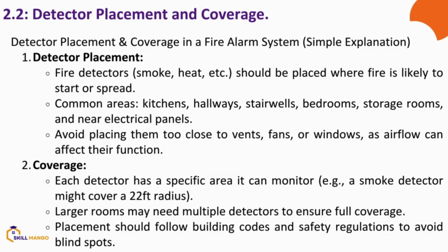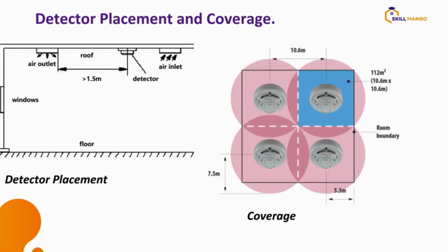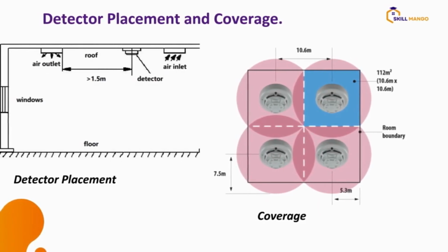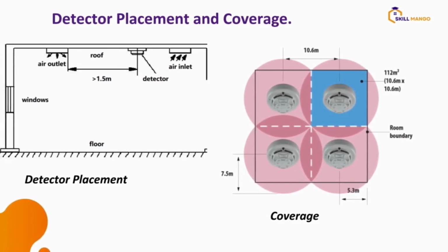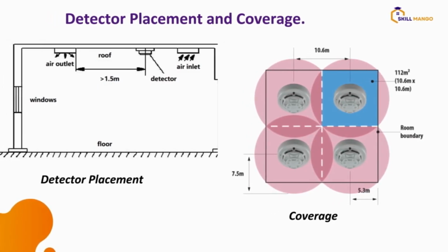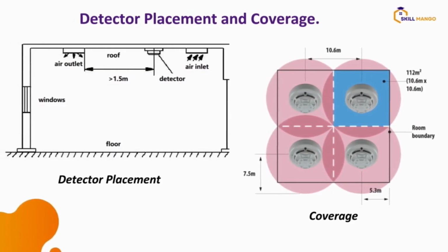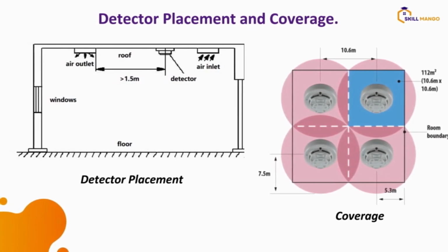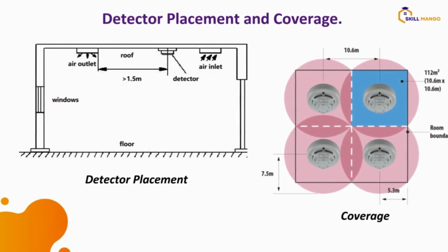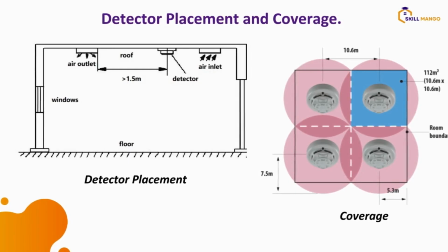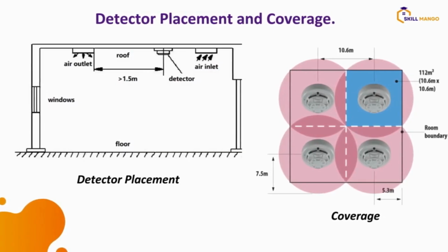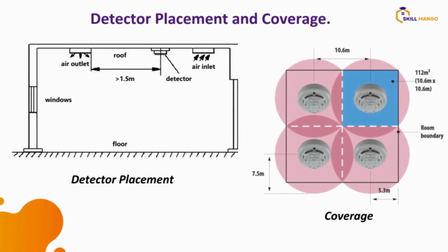Then also let's go to where we can see a typical diagram. Okay, so this varies from detector to detector. You have to pay attention to the manuals. So when you buy a detector you've not used before, you're using it for the first time, the standard procedure is for you to carry the manual and see the angle of coverage before deployment. Study the manual, so you can know the standard heights and the angle of coverage of the detector.